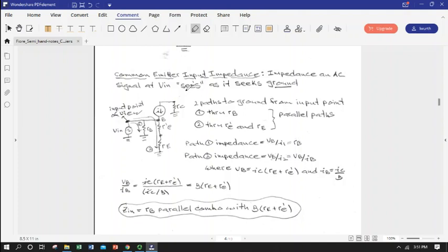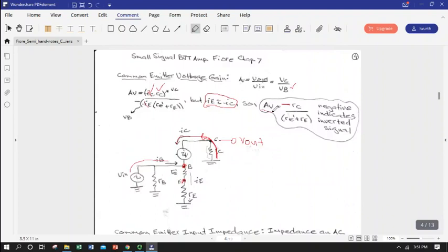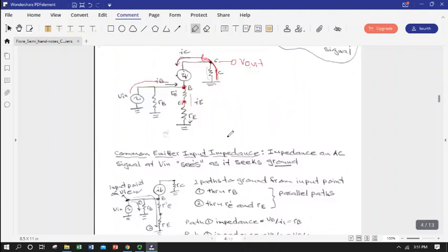Now remember when we did general amplifier characteristics, we discussed how important it was to understand input and output impedances, because those could really have an effect on whether or not we're going to get all of this voltage gain when we actually draw current through our load resistor, or when we have some resistance with our input signal. This A sub V is our theoretical voltage gain. So we need to define our Z in, our input impedance, and Z out, output impedance, in case we have some non-ideal inputs and outputs.